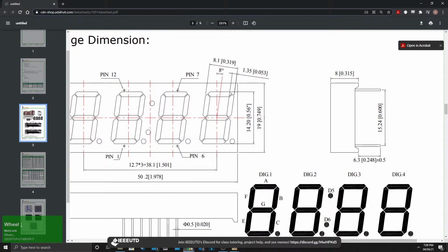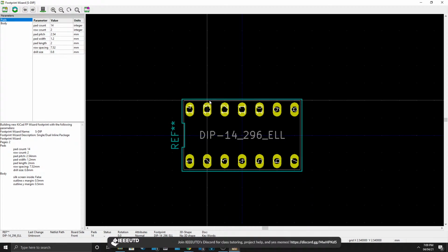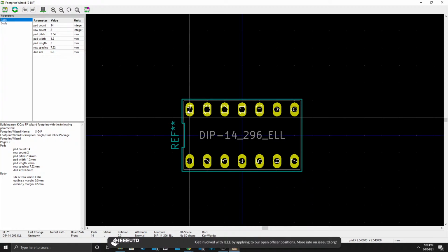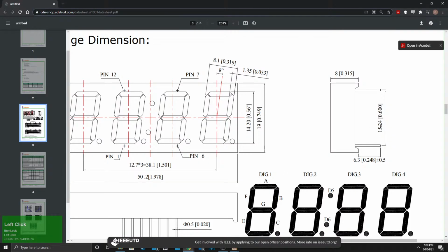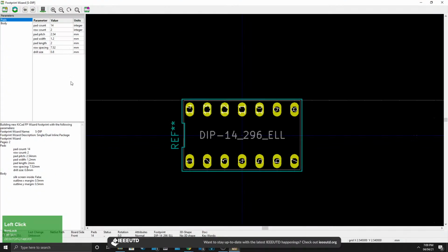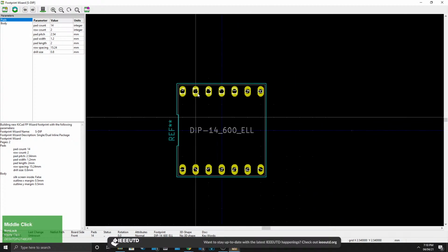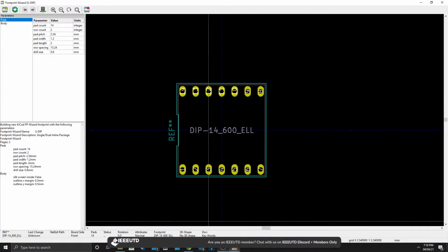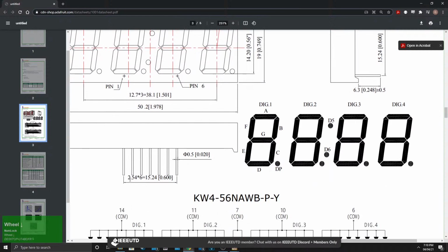So what I'm going to do is go in here to the row spacing, which is the spacing between all of the rows, and these separate things are columns. So these two are rows, and the row spacing is 15.24 millimeters. I can come here, type 15.24 millimeters, press enter, and now you can see it is very similar. Another parameter you can see is 2.54 times 6.